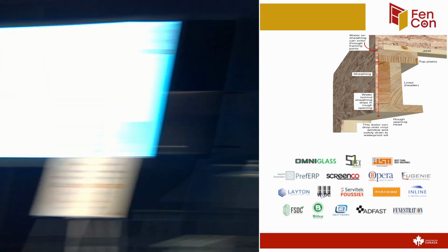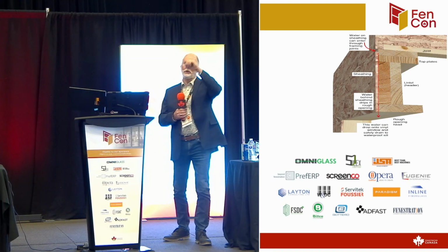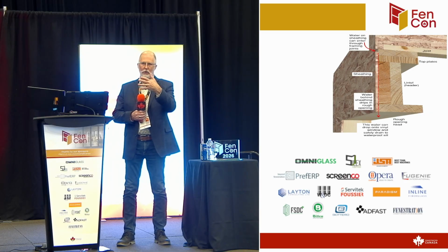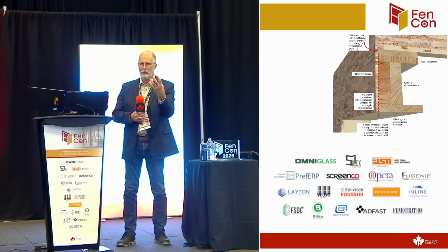Yep. And I agree with you. It's about the quality of the workmanship. But if you were to do a couple of things, first of all, if you look at the installation and think about if you don't get the air seal on the inside and the wind blows through, okay, what's that going to create in the cavity? Moisture. Moisture falls to the bottom, it drains out. Has it hurt the structure?